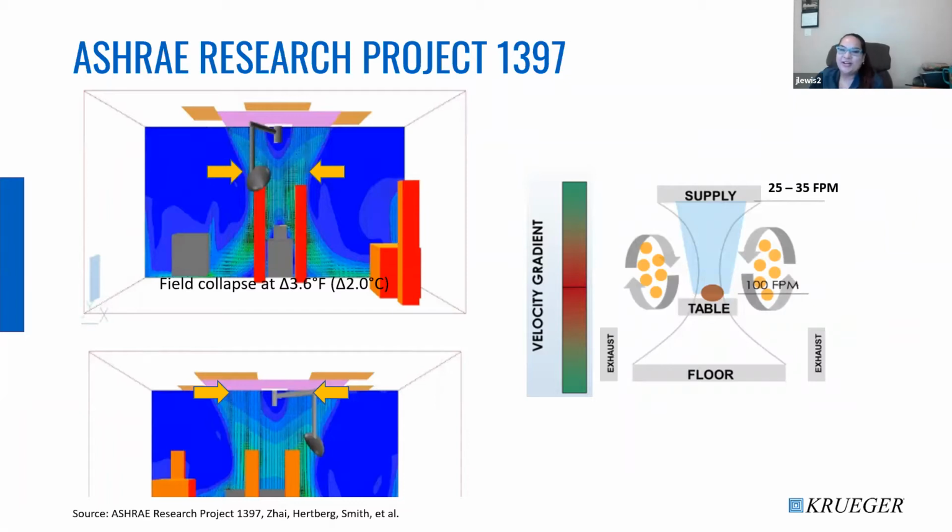Okay, so starting off with the design of operating rooms. Often we see that laminar arrays are being used, and some of the challenges that an all laminar flow design can cause is airflow collapse. So the amount of collapse and acceleration is affected greatly by the temperature difference between supply air temperature and room air temperature. This collapse is also referred to as coalescence. And you can see the air collapses in an hourglass type shape on the screen. And when this happens, the velocity of the air also increases as that air collapse and that coalescence happens.